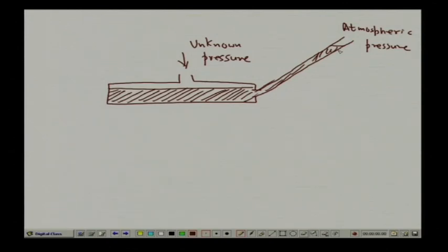So, what will happen, you see the liquid will come down here. Now what is the difference between the inclined tube manometer and the well type manometer? You see, in the well type manometer this column is straight. Now, here the liquid, since the height is the same, has to travel a longer distance here.